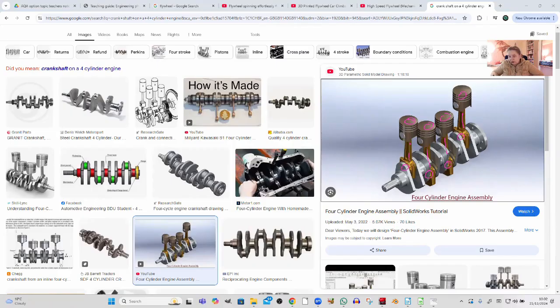And you can see that although it's got kind of gaps in it, this thing rotates around that axis of rotation. So this is the crank, and attached to the crank at one end will be the flywheel. That's how an engine is constructed, and so the pistons push down, and the crank effectively turns that linear motion, which applies a torque, into rotary motion to make the thing go round.